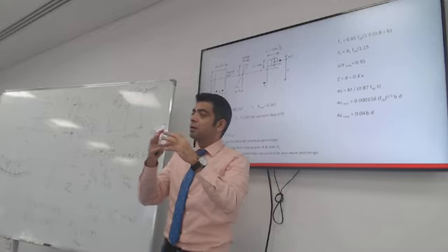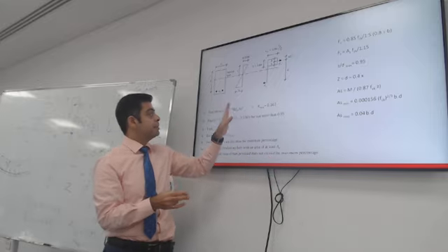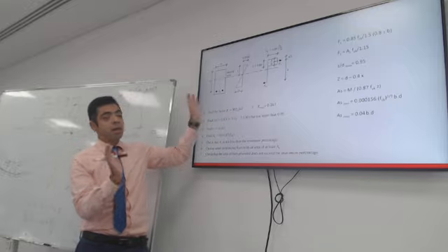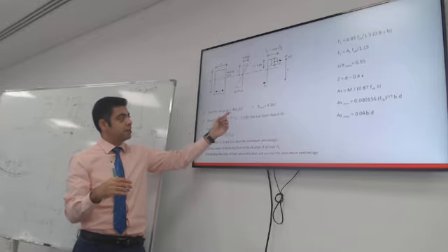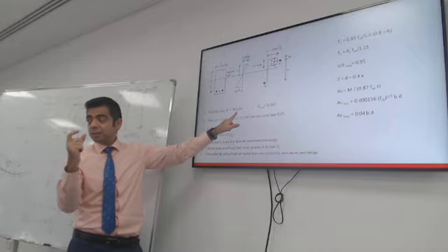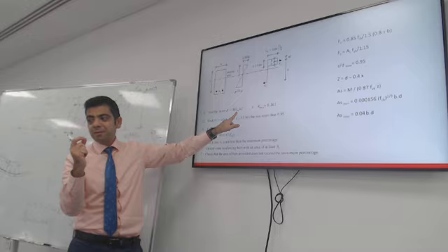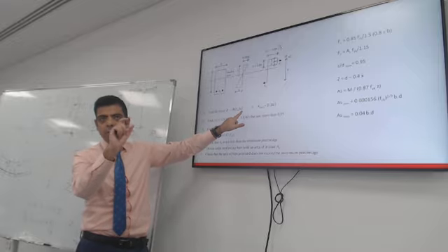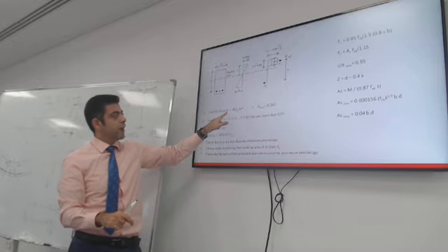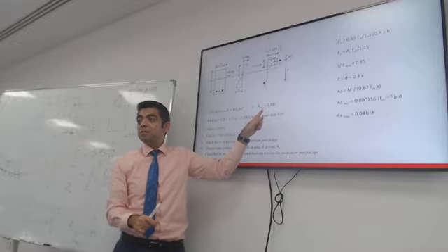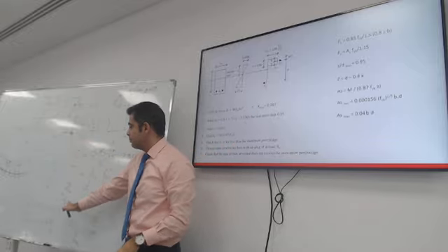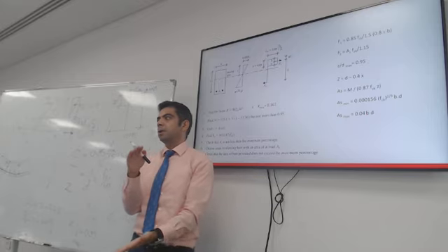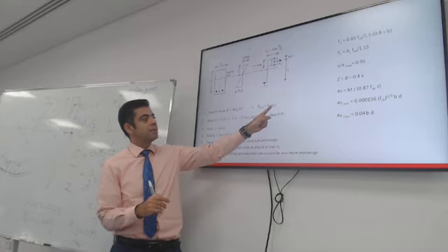To simplify this equation, let's assume a factor called K. The factor K is the ratio between the actual moment on the cross section and the characteristic compressive strength, divided by the width multiplied by d squared. And this factor K also needs to be limited. It's derived from the same ratio. The factor K should not exceed a certain limit. It should not exceed 0.167.